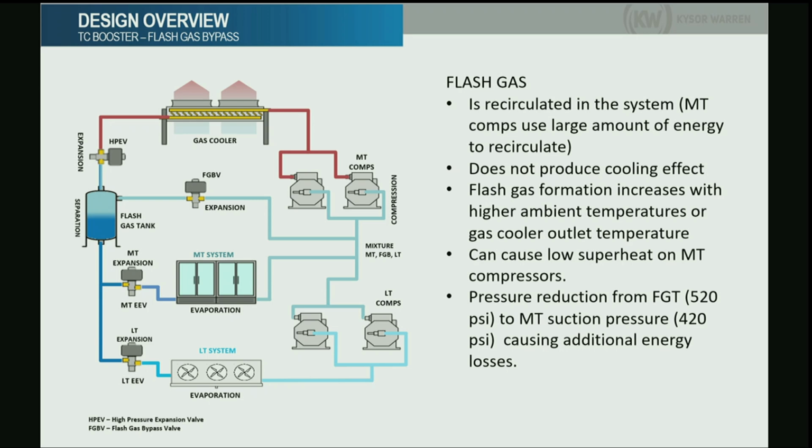From here, you need a valve that will increase your discharge pressure on the medium temperature compressors, because depending on how you do it, you can have different flash. You can have a tank for hot gas defrost only, or you can take your flow going back to the flash tank. If you go back to the flash tank, you need to increase your discharge pressure on the low temps higher than the flow hot back valve, to increase your pressure going to the flash tank.